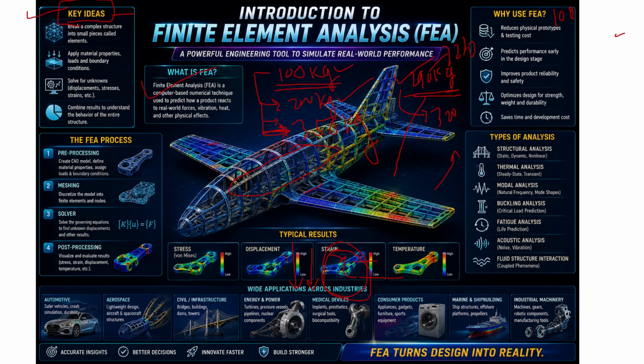As you know, if you are going to iterate the loading condition for 5 different loads, then we have to apply the loads 5 times physically. It will take a lot of time, cost, and technicians to remove one load, then apply another load, and again remove that load of 200 kg and apply 350 kg. That kind of time consuming process can be reduced from lab to the virtual thing. That is the thing behind saves time and development cost.